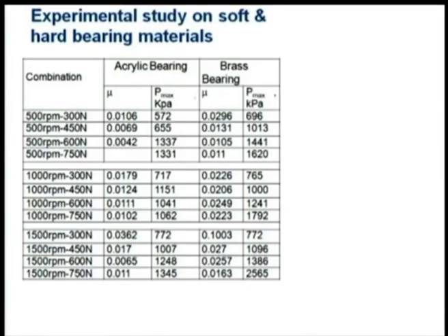So, the interesting thing is that material properties play an important role in finding out what the maximum pressure will be. This is good to learn from a mechanical engineering point of view. Many times in mechanical engineering we design a component and subsequently select the material based on the maximum pressure, without thinking that the maximum pressure itself will be decided by the load or by the material which is getting deformed. We generally avoid the deformation and then calculate maximum pressure, while in reality, in a practical situation, deformation will change the maximum pressure value.